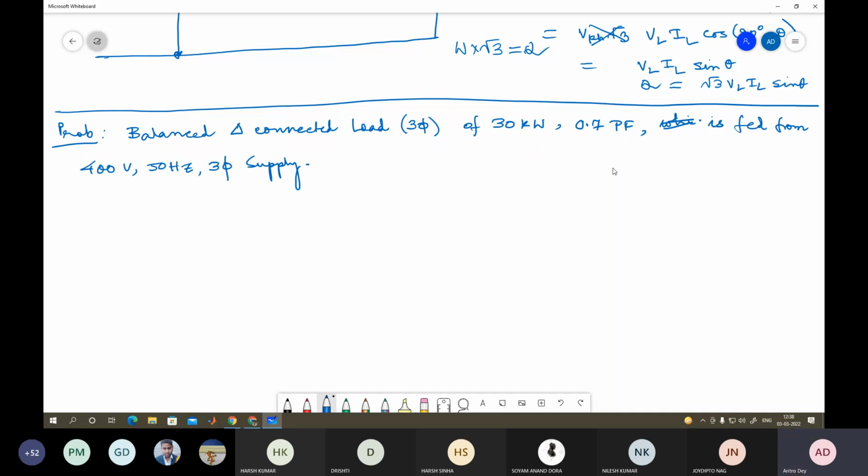Now you can see that if your power factor is 0.7, it is okay, but in some cases power factor can even go bad for a highly inductive load. Then what to do to improve the system stability and retain the measurable power? For the supply you should use a capacitor bank to improve it. So that is called power factor improvement.